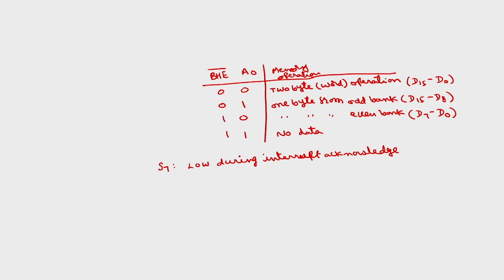So whenever the microprocessor is executing some program, as we have discussed in the last class, any external device can interrupt and it can ask the microprocessor to execute some emergency task. So during that time it will request the microprocessor through INTR or NMI. Okay. So whenever the microprocessor receives the interrupt signal, it completes the execution of the current instruction.